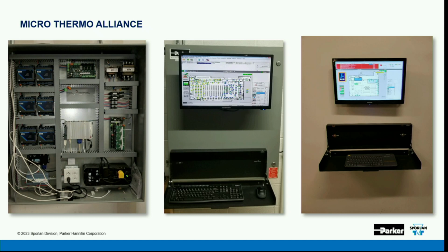Let me talk about that now. When you start Microthermo, you go on the landing page. You find the case controller or the MT700 or the gas cooler node, whatever you want to work on. Find the virtual node. You're going to open it up. You're going to go to the Install tab, and there's a button that says Install. And a cartoon character, an arm, is going to say, press the button. They're telling you to press the service pin button on the controller.